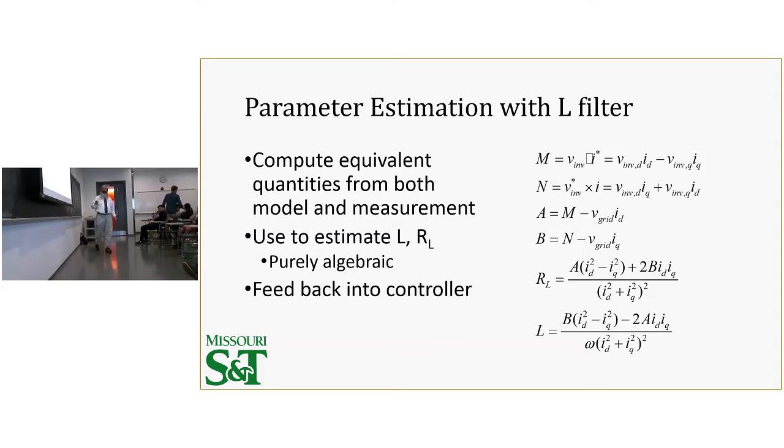So at any rate, we don't actually know the inductance and resistance, but we can use that knowledge that we have from the two different perspectives on it to compute our estimated resistance and inductance. That's important because when we're doing all of our control in this harmonic series, as we get to higher order harmonics, the inductance especially matters a lot, and so we need to have accurate estimates of it.